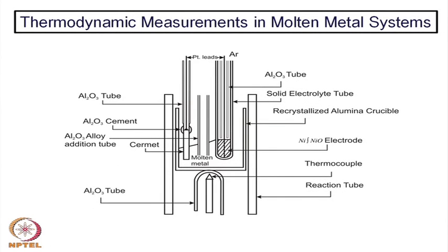Now, in addition to this kind of gas phase measurement, where one needs to measure the oxygen ion concentration of different gas mixtures, even of different industrial gases, another very important area where these sensors are extensively used is in furnaces. Just like in an automotive engine, you have a combustion process going on in industrial furnaces, even ceramic furnaces and ceramic kilns. Many of the ceramic kilns today are fitted with oxygen sensors, Zirconia sensors or oxygen measurement sensors.